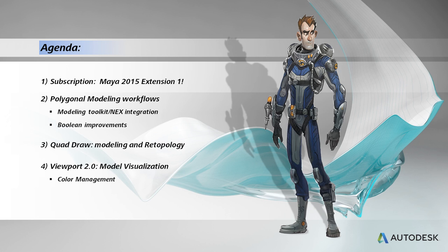Now that is part of the modeling toolkit, but I feel it's important to take a look at the modeling toolkit Quad Draw tool within the two major areas of how that tool can work. So I'm going to divide that up into a couple of different ways. One of them is adding geometry to an existing model, and then how you can work with that by drawing, or as I refer to it, dot drawing onto an existing piece of geometry and then building a whole new piece of geometry or a new piece of model. And the other one is this manual retopology workflow.